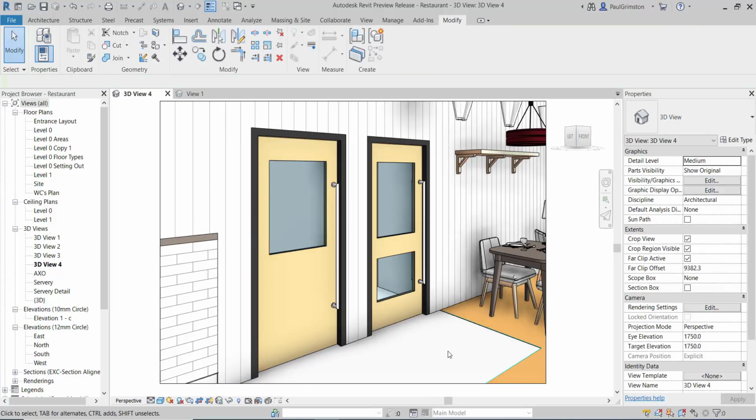Prior to this feature, we would have to use parameters to physically move the void objects away from the solids, and this can be problematic and lead to extended bounding boxes. This new functionality will allow a much cleaner workflow, and we can potentially reduce the number of families we need to create in our libraries. Obviously not just with doors, but anything that may need cutting, be it furniture, joinery, etc. I think this feature will be very useful in the future and is worth incorporating into our family libraries.